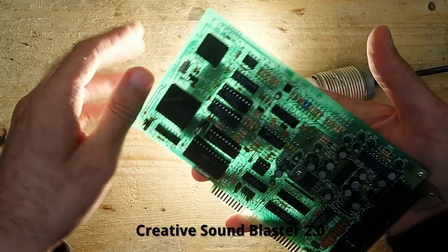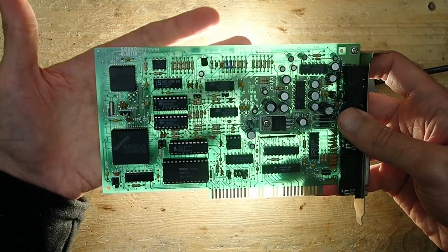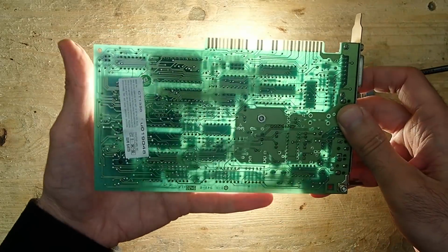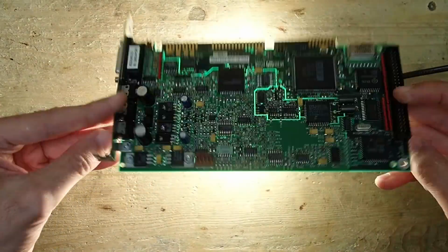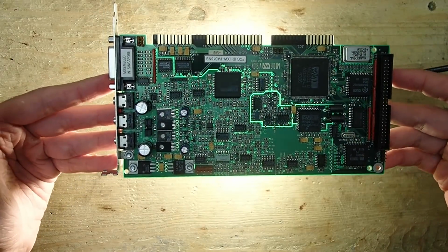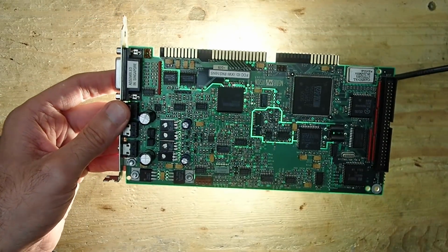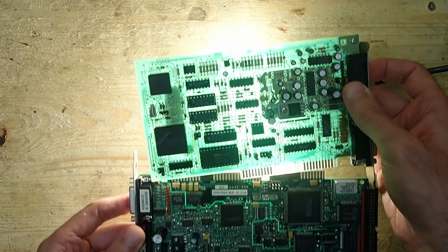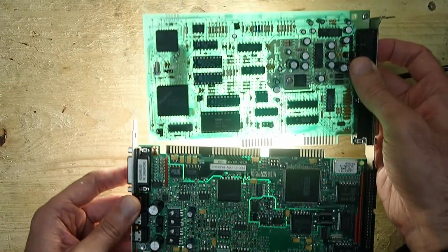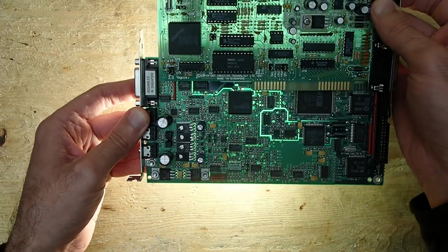If you hold the card against the light, you will see it shining through the PCB everywhere except where the copper areas are. The more expensive card like Adlib Gold or this Pro Audio Spectrum 16 have multi-layer PCBs, where a ground plane is even placed inside of the PCB. As you see, almost no light is shining through this one, and this is basically one of the biggest reasons why this sound card has such a high audio quality compared to, let's say, Creative products.